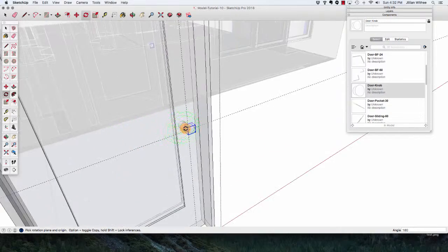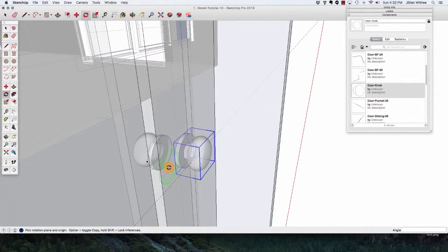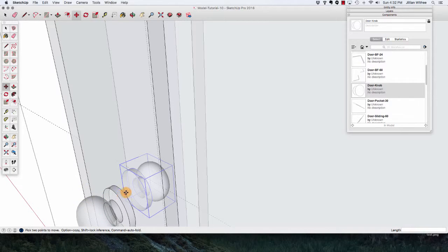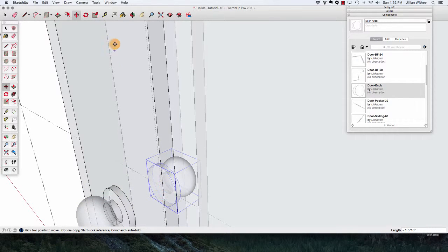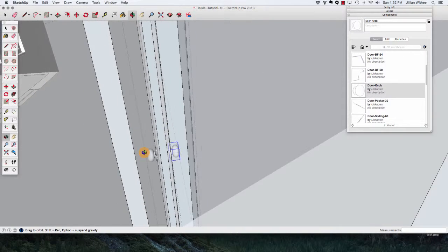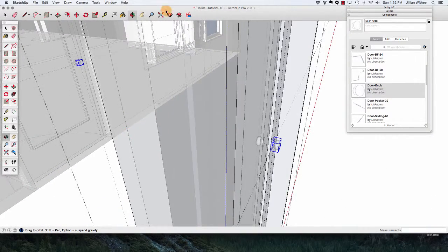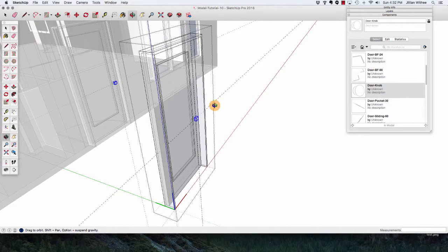And then if you zoom back in on that, you will see that it is rotated around 180 degrees, but that it's now out of place again. So if you activate your move key again, you should be able to get that center point and line it back up. In another tutorial, we'll talk about different ways for mirroring. What we really want to do in this case is mirror it and not just flip along it, but this technique will do for right now.